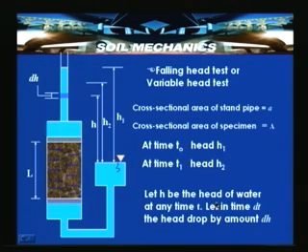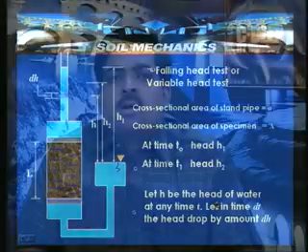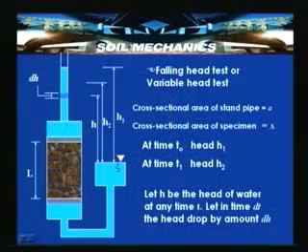Having seen the constant head test for determining the permeability of coarse grained soils in the laboratory, let us look into the variable head or falling head test method. Here, this particular arrangement shown has a soil sample which is relatively impervious, a clay soil sample placed at a certain unit weight and water content and surrounded by